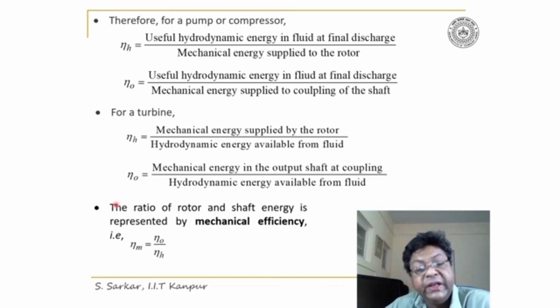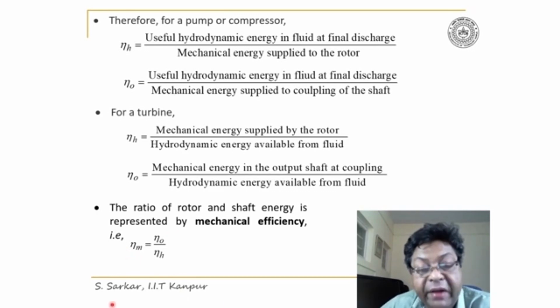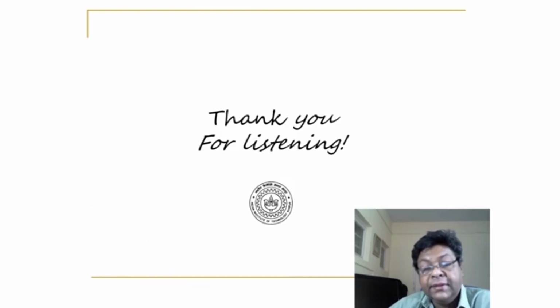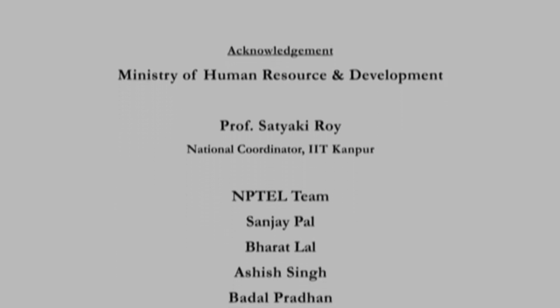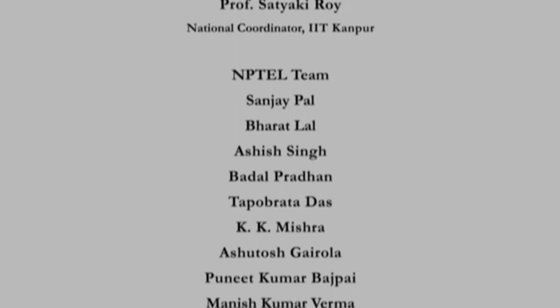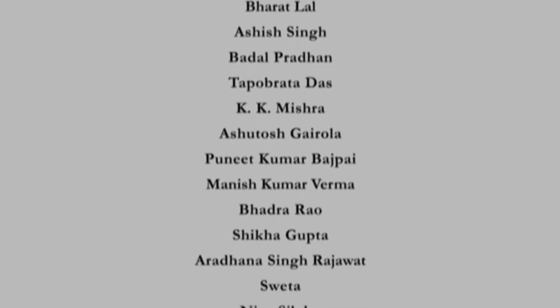Let's consider the conservation of mass. For the conservation of mass, I can write for a system dm dt is equal to 0. That means mass can neither be created nor destroyed. This leads to del by del t of the volume integral of rho d omega plus the surface integral of rho v dot eta dA is equal to 0.